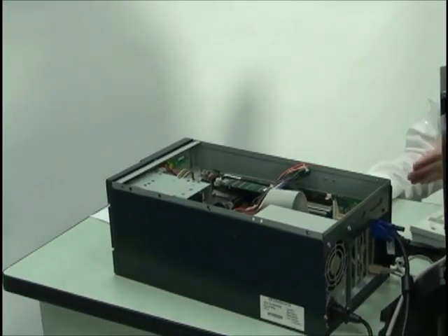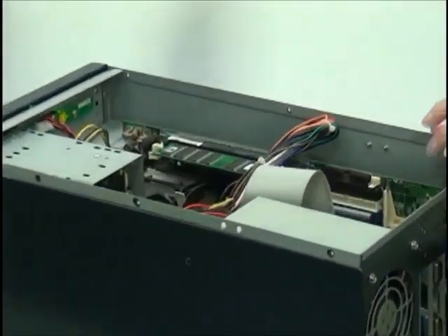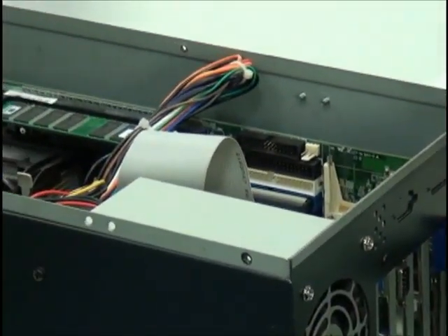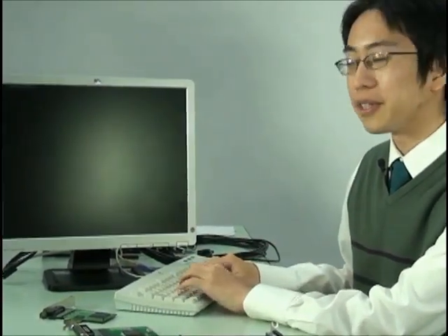What we have here is a system running DOS that has an ISA C168 serial card in it. And this is an 8-port serial card. So you've got 8 serial ports. Now, when you install a serial card, the first thing you need to do is to manually configure all of the parameters in both the hardware and the software OS driver. Once you've done that, you can plug in your serial devices, and hopefully everything works. But if it doesn't work, it's time to troubleshoot. And that's where Moxa's Diagnose tool comes in.